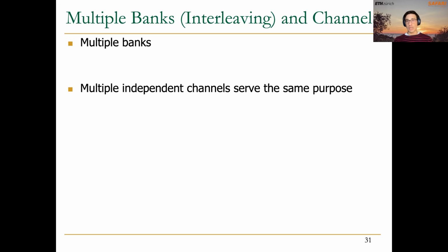Channels are essentially the same. We can have multiple channels. Remember that connected to these channels, we have multiple DIMMs, and we perform accesses to all these channels in parallel. So we can talk about bank level parallelism, and same as we can talk about channel level parallelism.